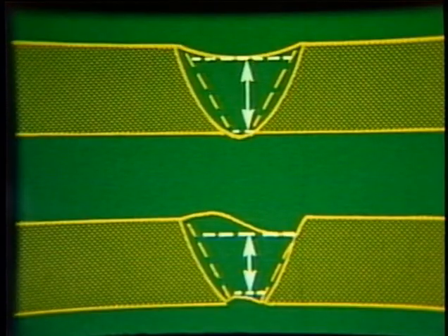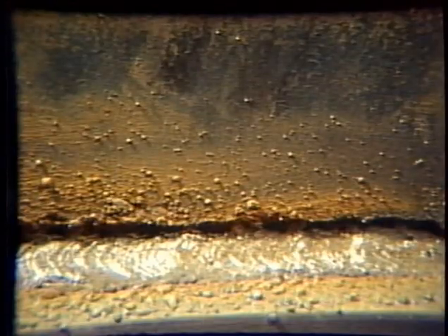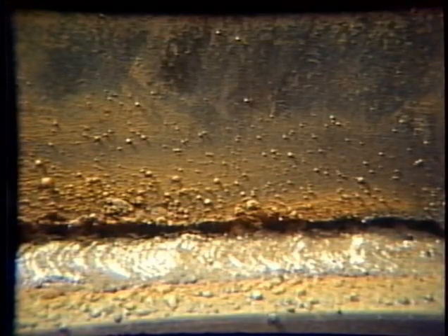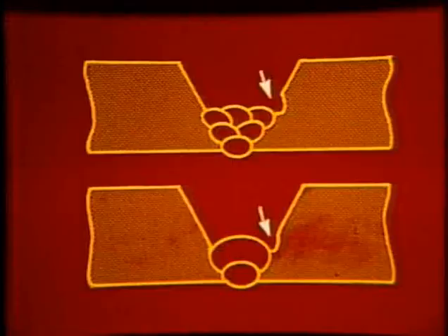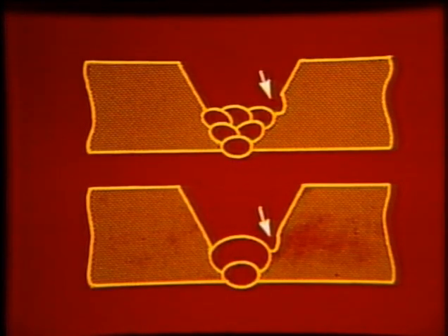A type of weld problem also related to weld profile discontinuities is undercut. This is best defined as a groove melted into the base metal adjacent to the toe or root of a weld and left unfilled. Undercut is most commonly found at the sidewall or face of a groove, at the edge of a weld or layer.